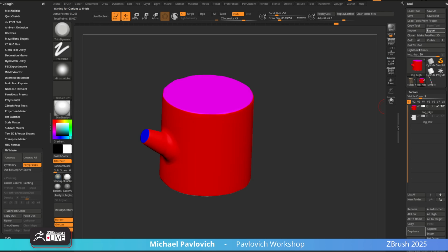So I'm going to go over here to save as file type FBX. And we're going to say log_high FBX on our desktop. And this is the only one that's visible. I can't bring the file export options here, but it's going to be visible. We're not going to embed any maps. Man, this is all reset. I just updated. Bin, we're not going to export cameras.